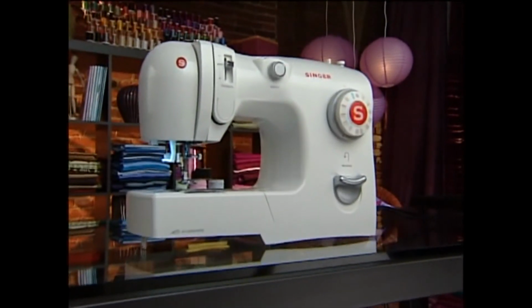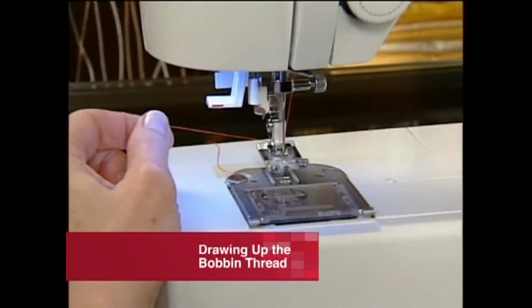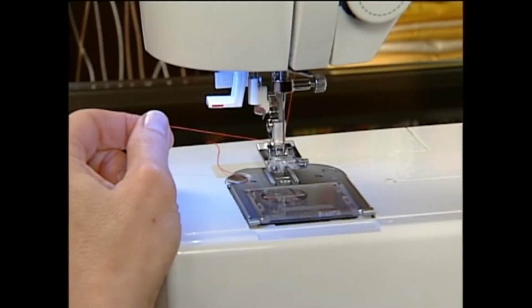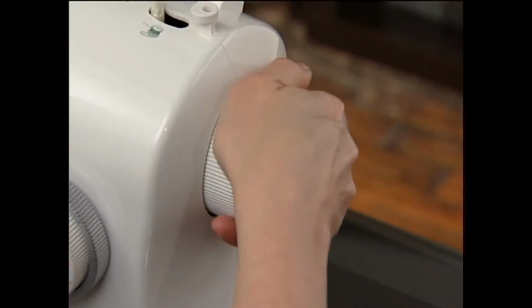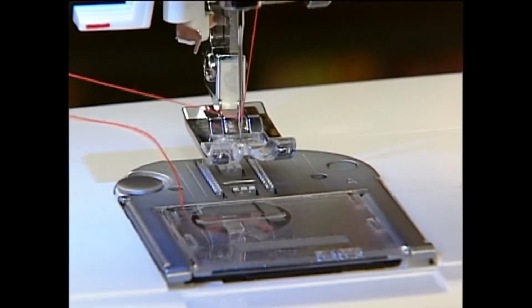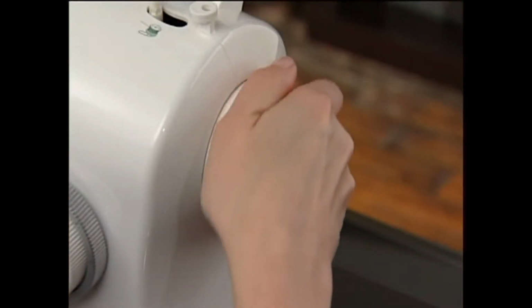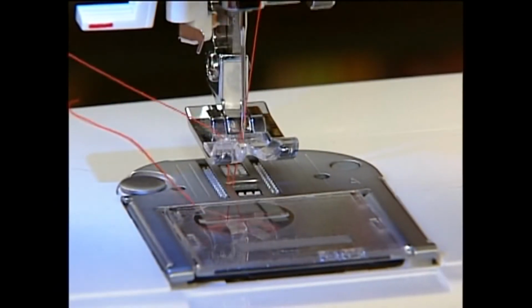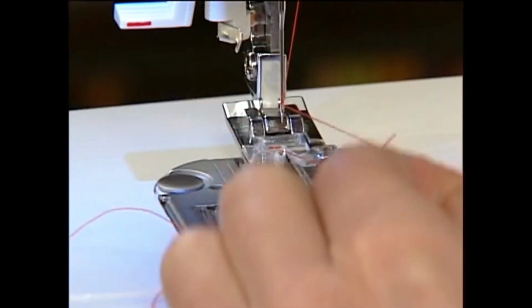Before you start sewing, you will need to raise the bobbin thread. To do this, hold the upper thread with your left hand. Turn the hand wheel toward you or counterclockwise, which will lower and then raise the needle. As you turn the hand wheel, lightly pull the needle thread. The bobbin thread will be drawn up through the hole in the stitch plate.